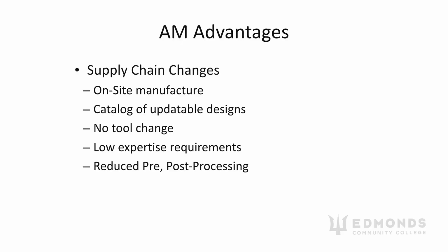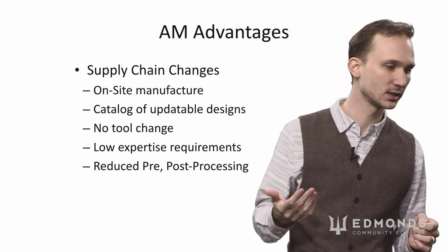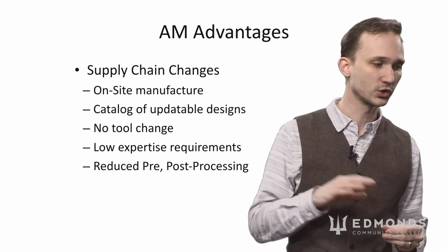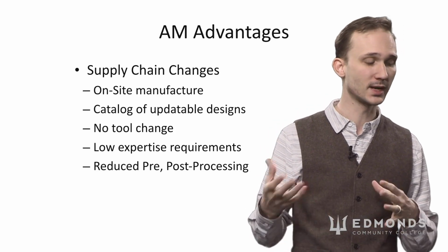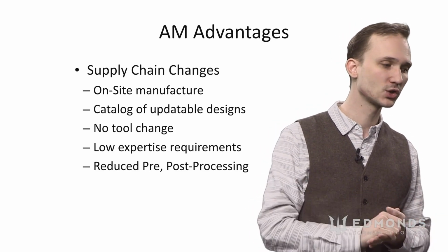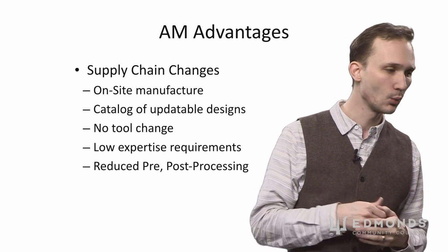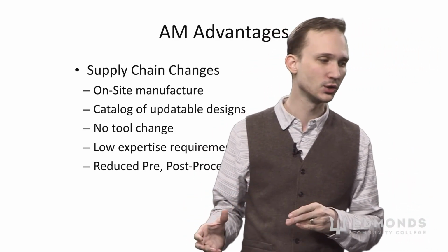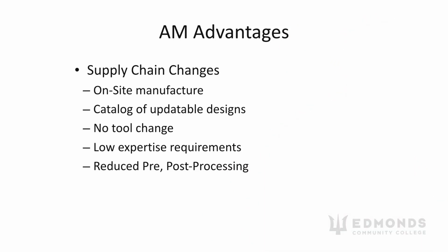So in terms of changing our process from brainstorming to deciding how we're going to make our final product, additive manufacturing also gives us the chance to consider whether it is a good part for additive manufacturing, whether storing it is costly versus producing it on site, whether it is a critical part that may be in low demand, so we don't know how often it's going to be used or how much it's going to be customized when we do produce it. And we also have to ask the question whether it's more efficient for us to store that raw material, which may change over time, which may age.